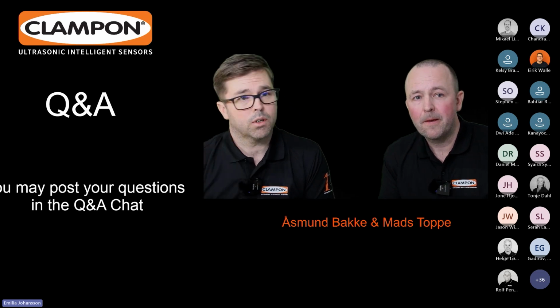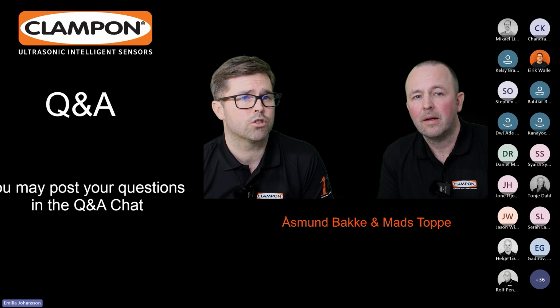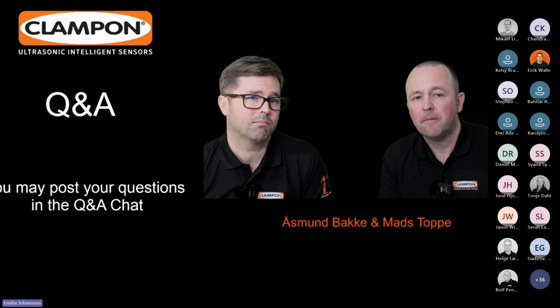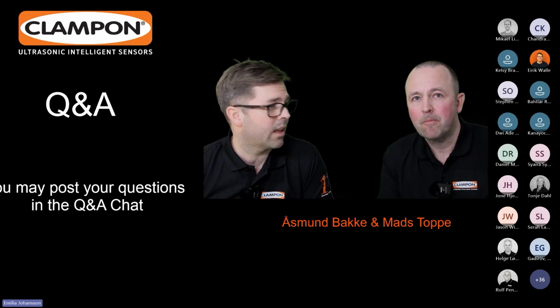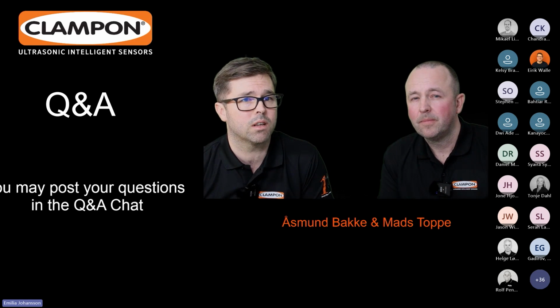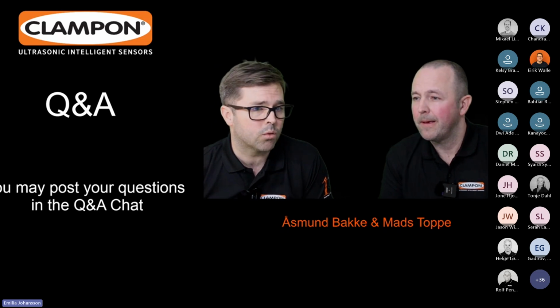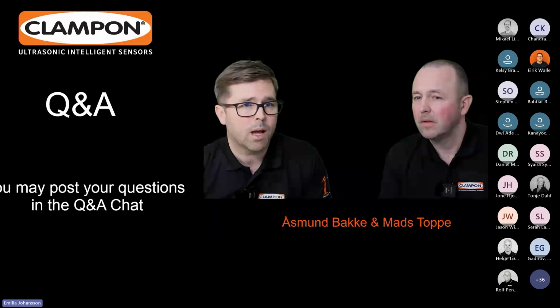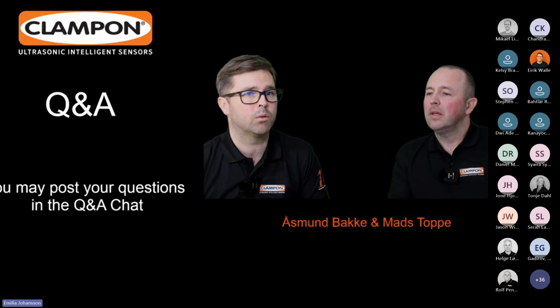There is another question about almost the same thing. He asked if it's possible that the sand monitor can't detect fine sand production at low velocities, which means we are not detecting it, and then chalk can still be eroded. Of course, that can happen, but the first thing is, if you as a user of the system have control over what velocity is needed for transport and what type of particles you are producing, you can find out if you are in the zone where you may not be able to detect the particles.